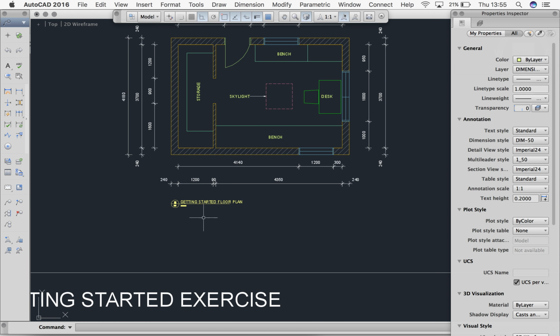For each drawing you do, you guys will need to make one of these. For every page that you have, you start numbering the drawing at the beginning again. So on page 1 you might just have the floor plan, so that's drawing 1 on page 1. On the next page you might have 2 elevations, so that will be drawing 1 on page 2 and drawing 2 on page 2. So you guys will need one of these.